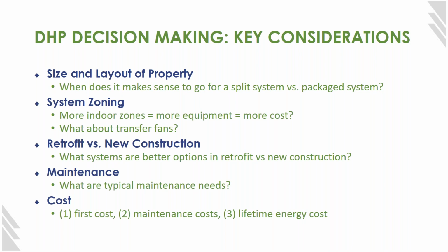If every apartment has its own balcony or outdoor patio, you've got a lot of area, I would say you should start with going with a split system because you have space for the outdoor units. You have the room for them. Really, a patio or balcony is an ideal place for a compressor because it's part of the apartment, but it's also relatively accessible and it's outside.